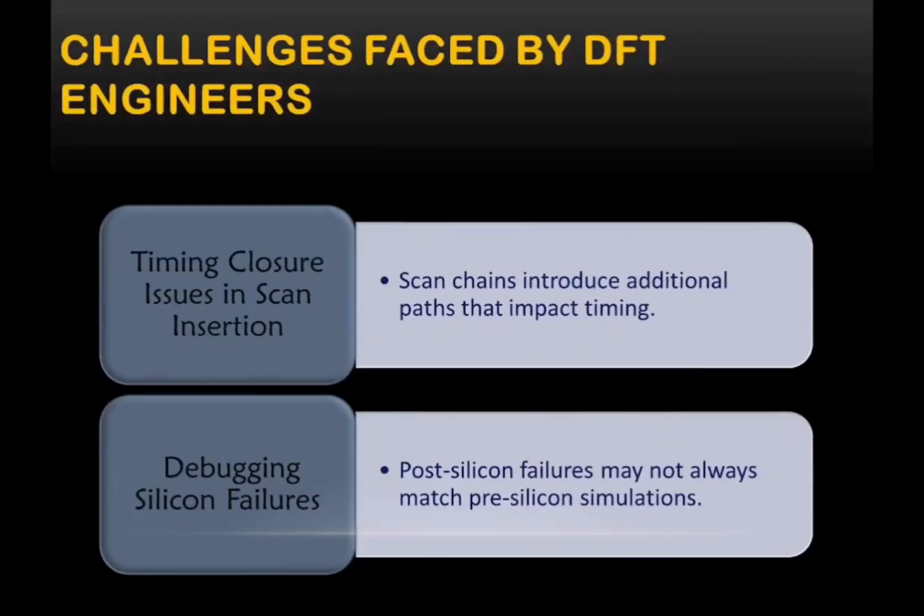So due to this, low power DFT methodologies must be implemented. The next challenge is timing closure. Scan chains introduce additional paths which impact timing, so proper scan chain balancing is required to meet timing constraints. And the last challenge is debugging of silicon.